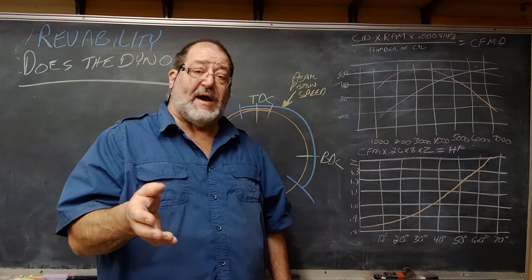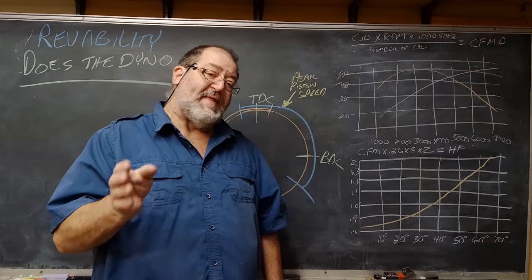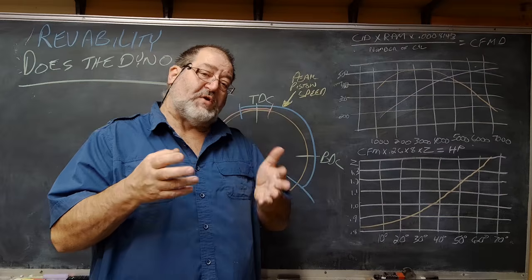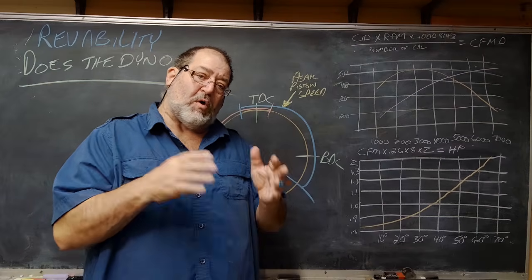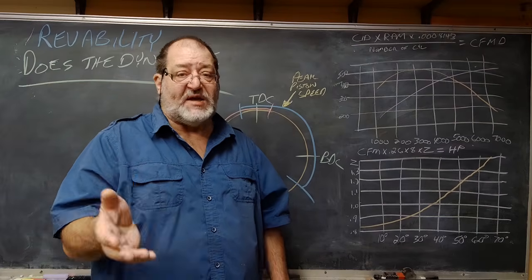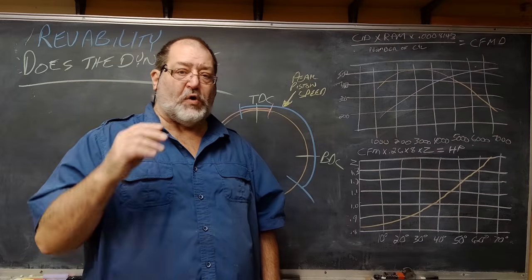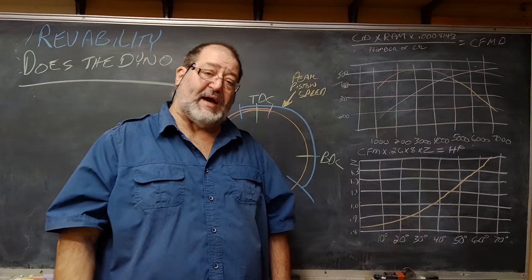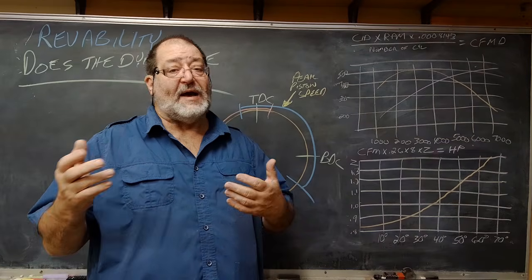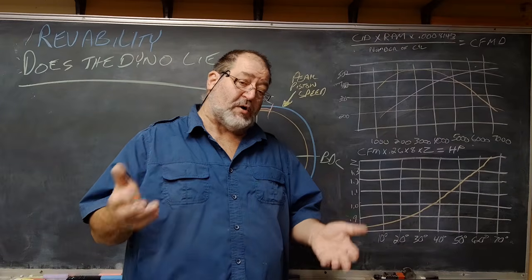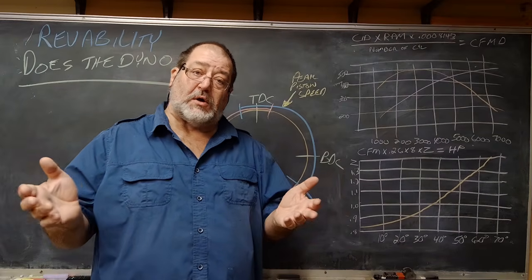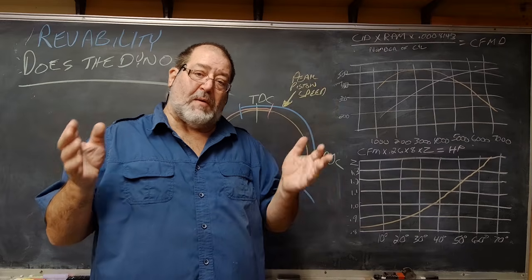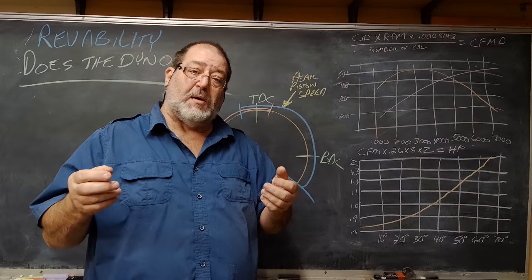And this is why some guys won't test that low, is they don't want you to see or hear what's going on in those lower RPMs. And then they'll try and convince you that 4 to 7 is fine. Well, 4 to 7 is fine in a drag racing application, but certainly not on the street, and even in some circle track, you may need a wider power band than that. You need to make the power band that you're working on better.